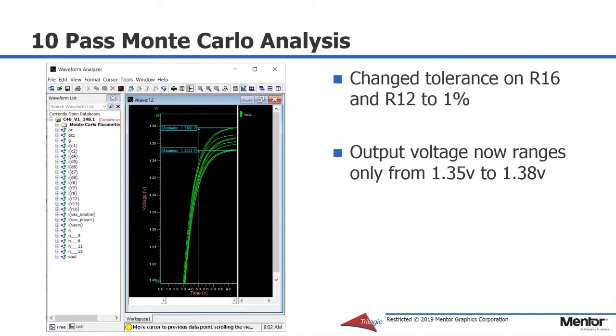Cost is always an issue with IoT devices, and we were able to quickly determine that we only needed to change the more expensive 1% components for 2 out of all the resistors. And as we know, in very high volume IoT products, such as ones that are going to be released at Home Depot or Lowe's or in other markets, just saving 1 penny of cost with a sale of 1 million pieces a year can save $10,000 in component cost.